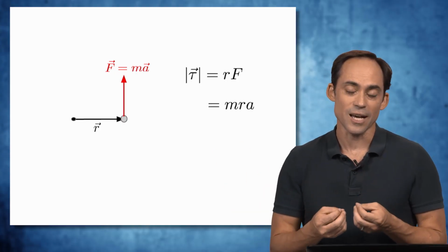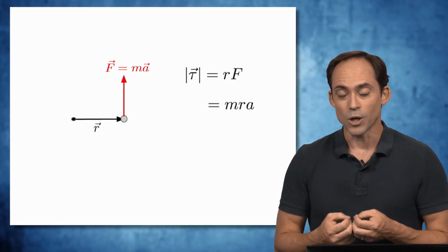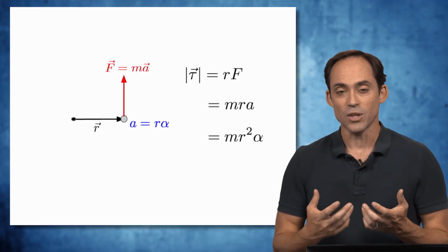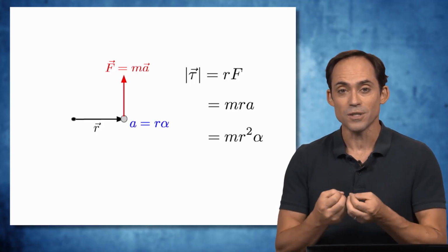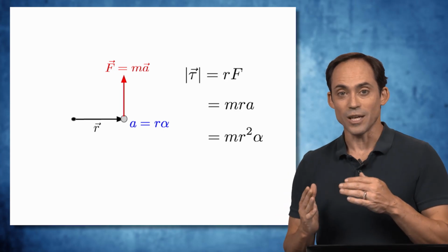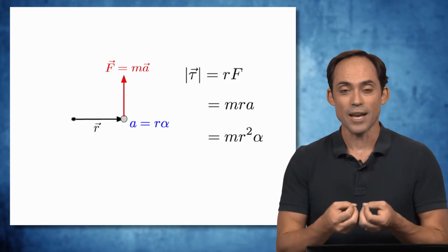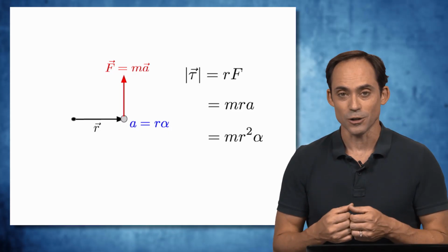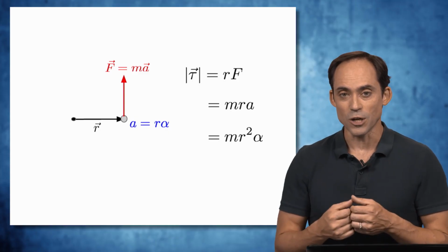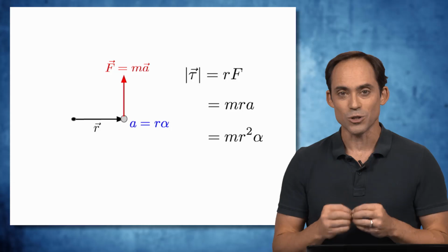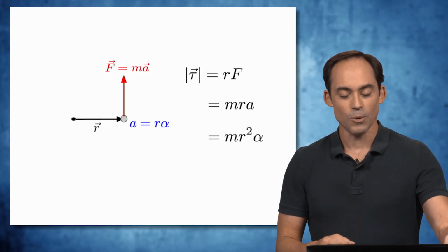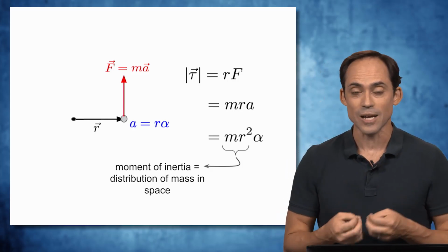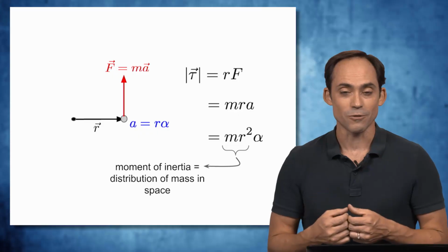And if we're looking at this as an angular acceleration problem, recall when we defined our angular rotational quantities, we could relate the physical acceleration, in the angular direction, to the radius times the actual change in the angular rate. All right, and that's the alpha term there. So if we substitute in those expressions to get out our actual radians per second squared angular acceleration, we see that we get this term out in front, which is m r squared, and that has the right units, mass times length squared, to be this moment of inertia.